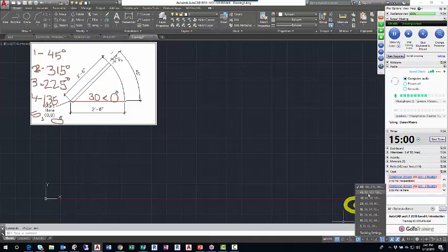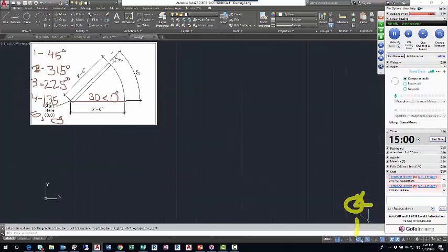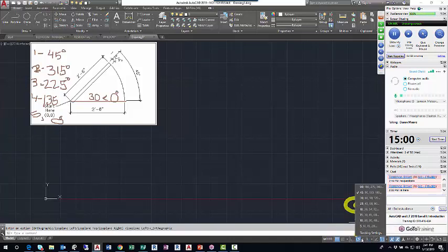Or in the case of our door, which is rotated at 45 degrees, I want to use 45-degree incremental angles. It doubles the number of incremental angles: 45, 90, 135, 180, 225, 315, and then finally 0 or 360. So I'm turning it on, and I'm going to confirm that this worked. As soon as you click your desired incremental angle, the menu drops out of sight. So I like to confirm it, and now I'm at 45 degrees.